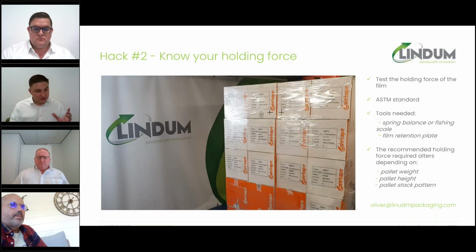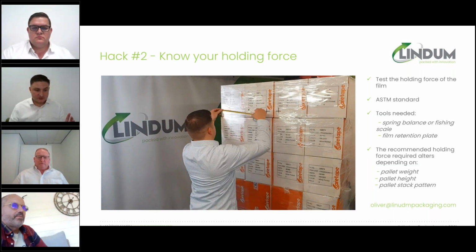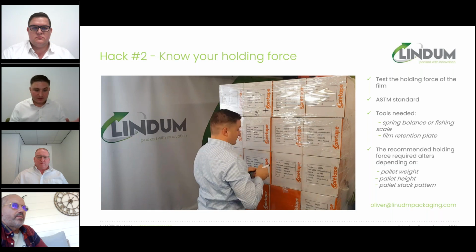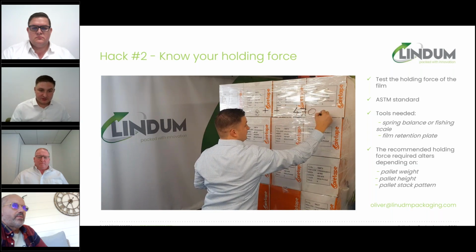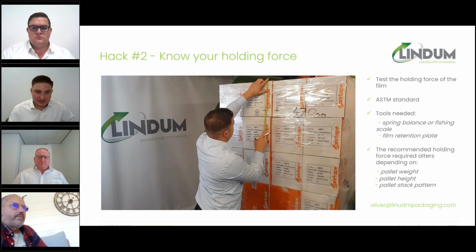So moving on to the second hack that we've got for you. This simple test shows how to measure how much holding force your stretch film is giving you. You'll need a spring balance or a fishing scale, and a retention plate, which you'll see in a second. You need to make 2 marks, as you can see, done on the pallet there.